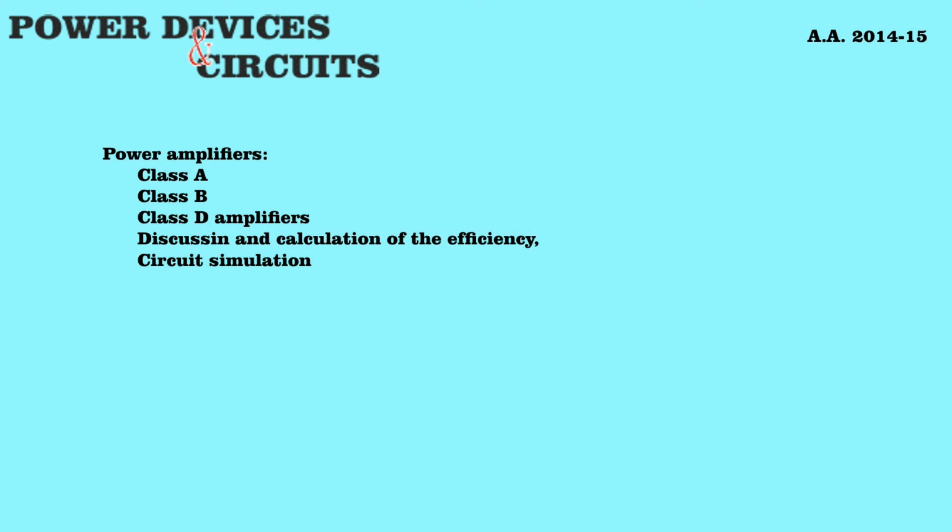This is a driving circuit that tries to avoid simultaneous conduction of the two devices. In the end, however, Class D power amplifiers can provide much higher efficiency than Class A and Class B. And this is not a very sophisticated design, it's just something that I made for teaching purposes.